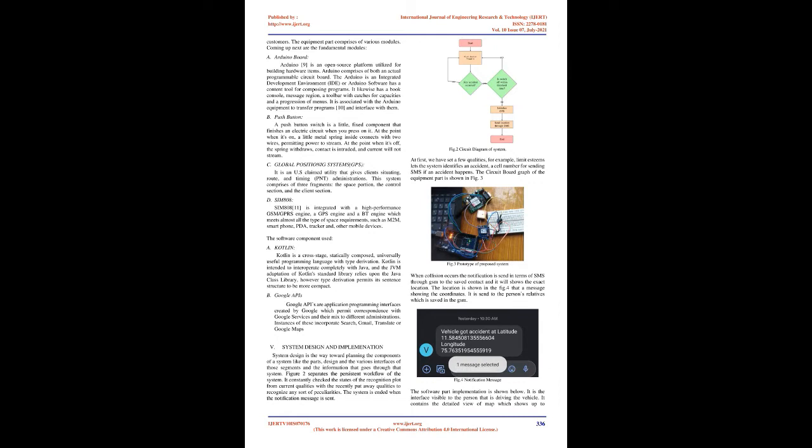3. Methodology. In this undertaking, we are attempting to make an IoT-based vehicle accident location and warning system utilizing an Arduino board and different segments, for example, GSM, GPS, and a push button. The block diagram of the proposed system is shown in Fig. 1. It comprises hardware and software segments. The efficient accident location and notification system comprises 2 stages, the detection stage and the notification stage. An Arduino-based vehicle tracking system utilizing GPS, the Global Positioning System, and GSM modules is utilized.